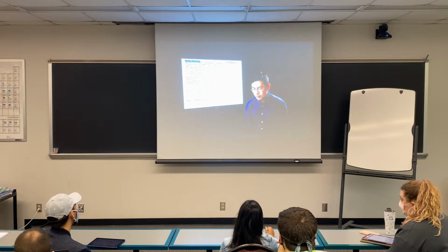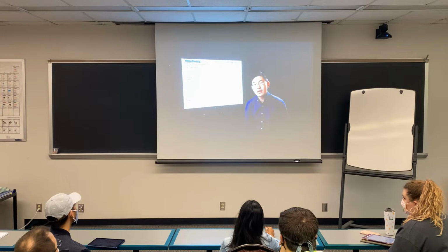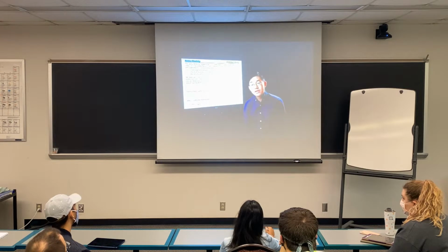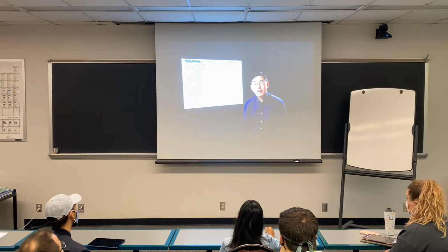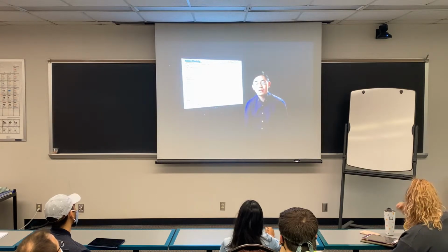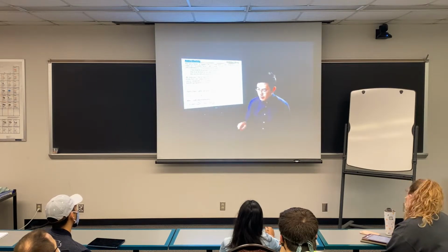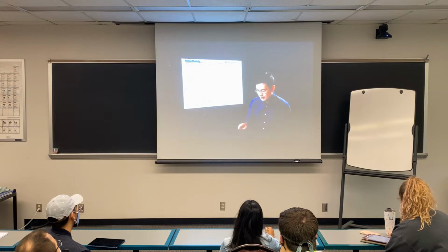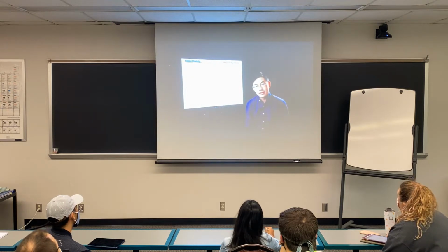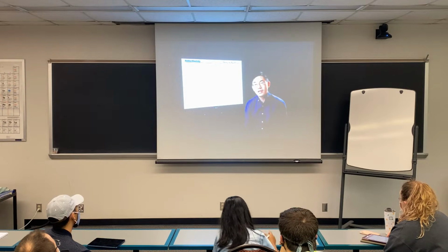And the second part is where we discuss that the initial network is isotropic. This usually holds true, and in many cases your rubber is going to start in an isotropic state. The volume remains constant, and that's pretty much the case. But again, there's always going to be a deviation from the ideal Poisson ratio of 0.5 for an ideal elastomer.